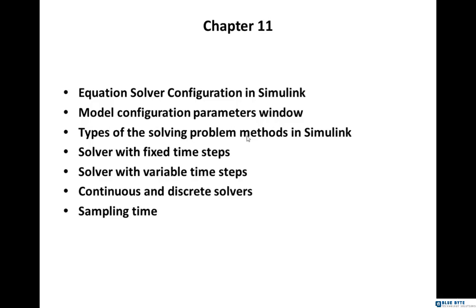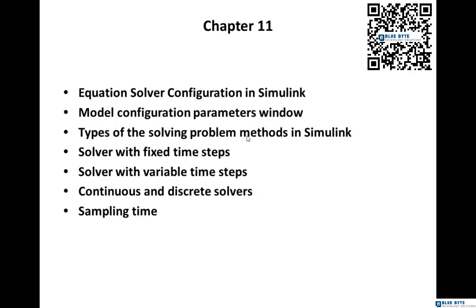First, I'm going to talk about equation solver configuration in Simulink, then how you can change its solver. Then we have the model configuration parameters window, which is the most important window in this section. Then we are going to talk about types of solving methods in Simulink: solvers with fixed time steps, solvers with variable time steps, continuous and discrete solvers, and finally the sampling time.